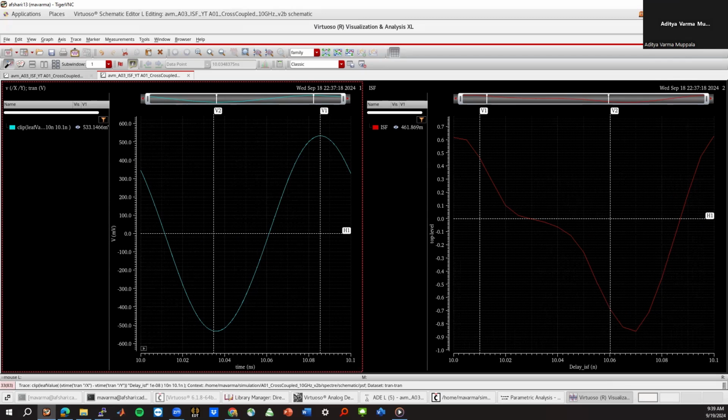I mean, this is a very slow approach, of course, because it's transient simulation. It takes a long time. In future videos, we will have to look at how to generate the ISF using periodic transfer function, PXF simulation. But to do that, we first need to introduce the PPV model, which will take some time because that's a little bit more technical. So we'll develop the PPV theory. Actually, before that, I will show you how to simulate cyclostationary noise sources, so the noise modulation function. And then once we do that, that will complete the ISF simulation part.